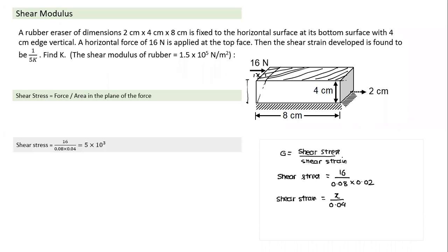Once you get shear stress, using this formula, we can easily find shear strain. Shear strain will be shear stress by G. This stress we divide by the value of G, and I get the value of shear strain. What does 1 by 15 indicate? In radian terms, it will make an angle. So whatever the height is, the deformation will be 1/15th of that height.